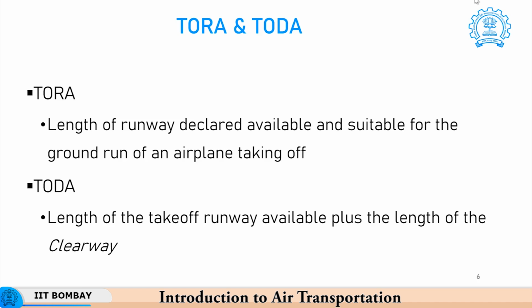The TODA or the takeoff distance available, on the other hand, will be TORA plus some other length which is required for clearing the obstacle height. So, it is the length of the takeoff runway available plus the length of the clearway. So, now there is a new term called a clearway. So, let us define what is meant by a clearway.